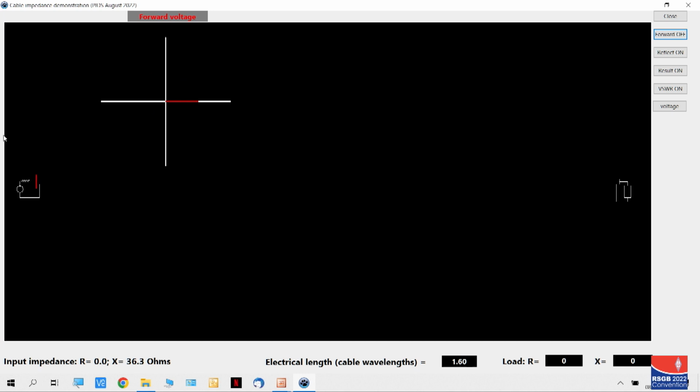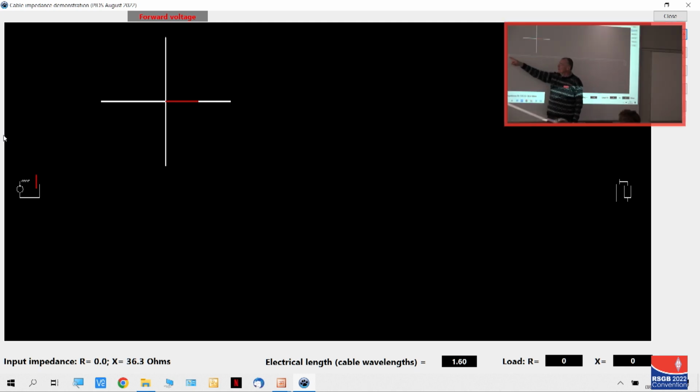And so what I've got here is a phasor representation of the voltage at this point. You see this red bar here, wherever it is, shows the point at which you're sampling the voltage. And this is your phasor diagram, and I've started off by having the voltage horizontal on the diagram. It doesn't really matter where you start off, but you've got to make a choice. So horizontal on the diagram here. The length represents the amplitude, and we don't have another one, so it's just along here.